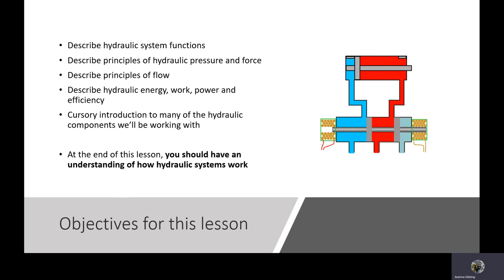This actuator down here is electrically operated and is just what we call a spool valve. And it just goes back and forth and shunts the fluid through these different conductors to make the linear actuator indeed work. Pretty standard application for a hydraulic circuit.